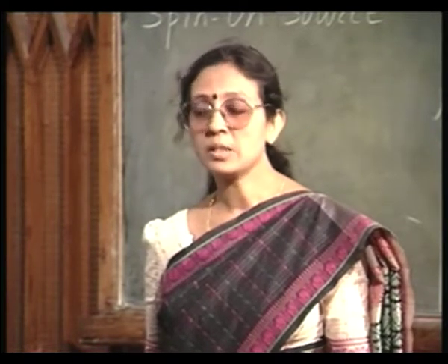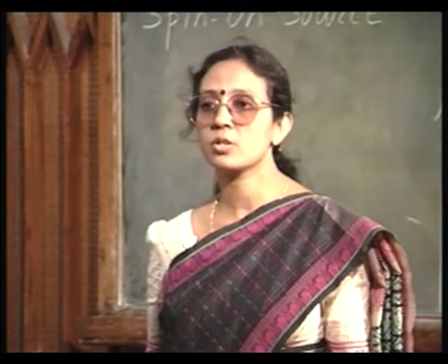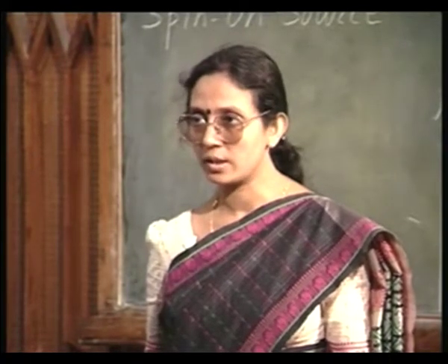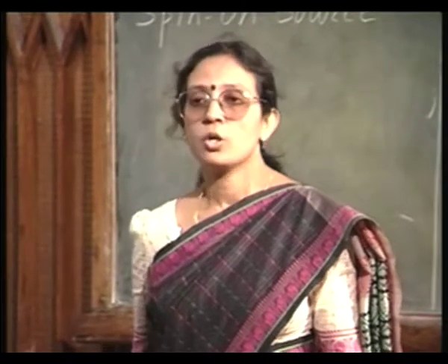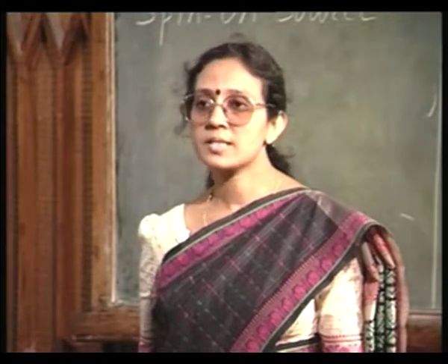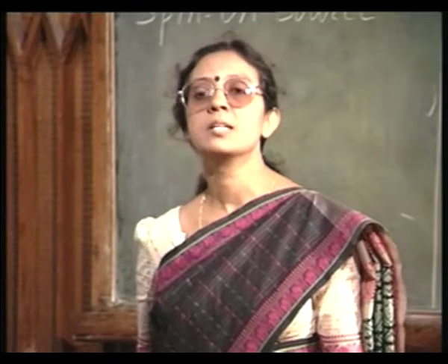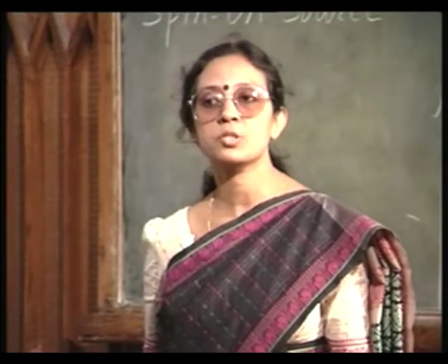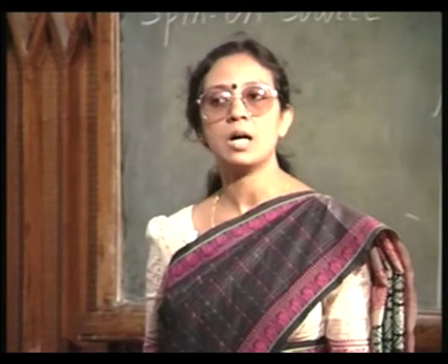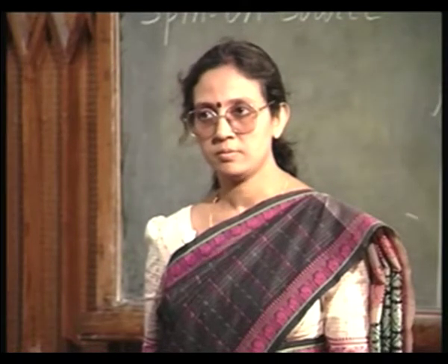So, what is going to happen? What is arsenosilicate glass? It is a combination of As2O3 and SiO2, just like borosilicate glass. So, you push this sample now inside the furnace. This arsenosilicate glass which is formed on top of the silicon surface is now going to act as the source for arsenic, as well as prevent the out diffusion of arsenic.